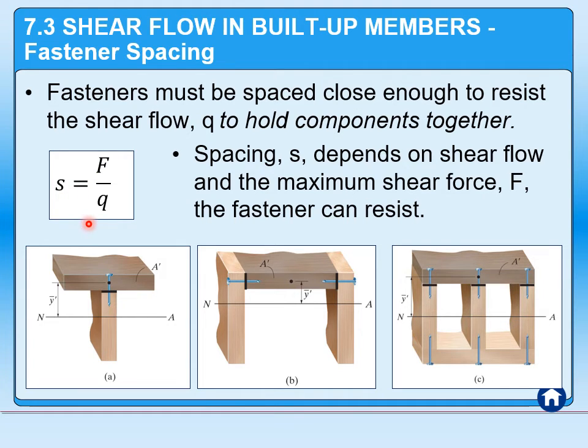By the way, the same basic technique would be used for analyzing a weld. So how strong does the weld need to be? Or to determine what adhesive could be used. Again, we want to determine that it would be strong enough to provide enough resistance to support this shear flow.